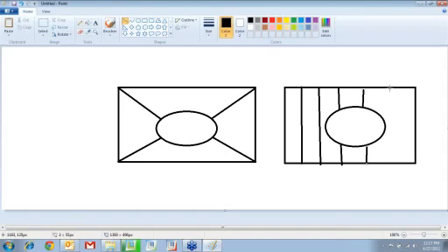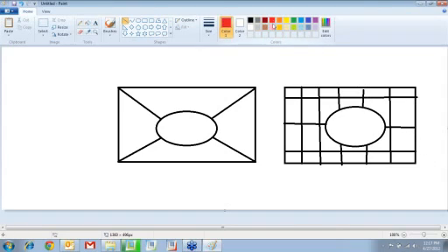The reason you would have to do much smaller elements in H-type FEA is to avoid something called a discontinuity or overlap between the element edge and the boundary. Now, we can see that the boundary is right here, right?